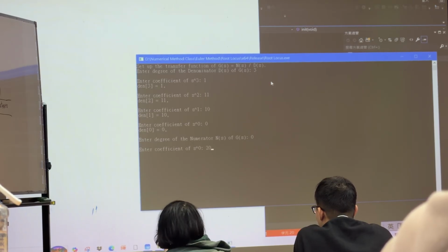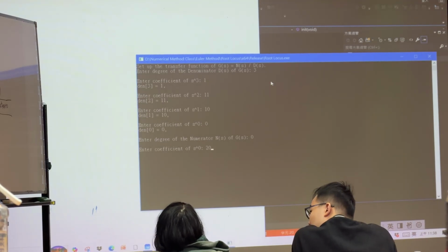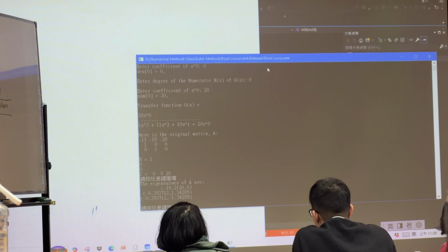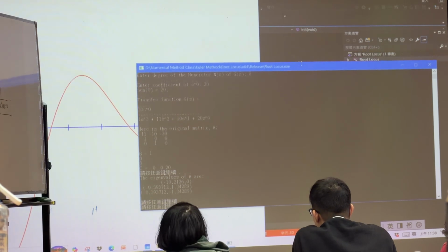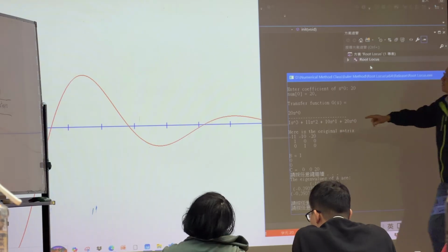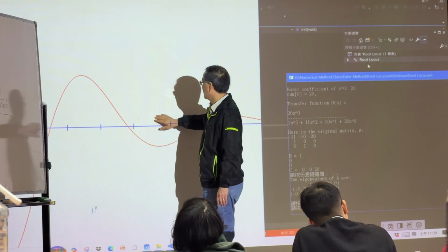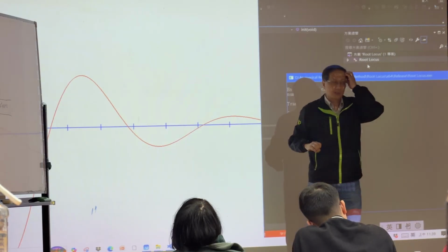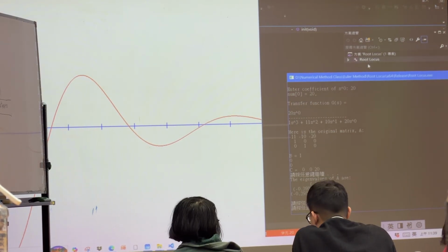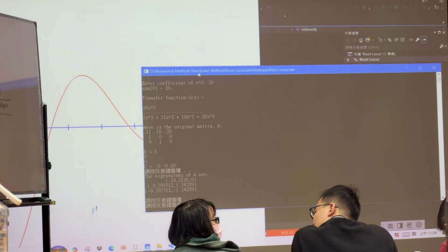We should see it rise faster, but the oscillation or the overshoot is even bigger. Yeah, you see here it gets higher, the response time is faster, and we jump like this. So you can tune the control parameters like this, by changing the k value.